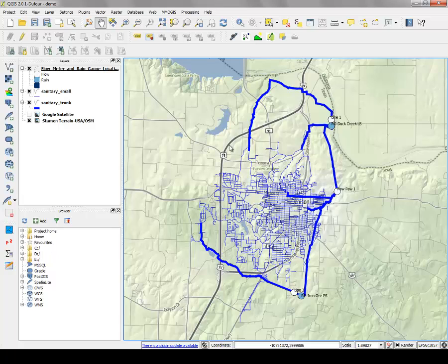So if you'll bear in mind this line 1 and Duck Creek, other things that are useful would be the amount of linear feet of sanitary sewer system that feeds into that system, as well as the actual area of the sewer shed. That's really principally useful for normalization. So if I have performance indicators based on volume of inflow or infiltration, or the combined wet weather response per surface area or per acre, that's something that a utility can use to help manage and try to set goals.